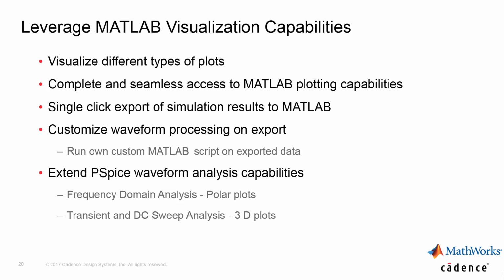We have also extended the PSpice waveform analysis capabilities so that if you're viewing any kind of data in the frequency domain analysis, you can take that data into the MATLAB environment and visualize that in a polar plot. Or if you're doing a transient and a DC sweep analysis, you can also visualize that data in a 3D format in MATLAB.